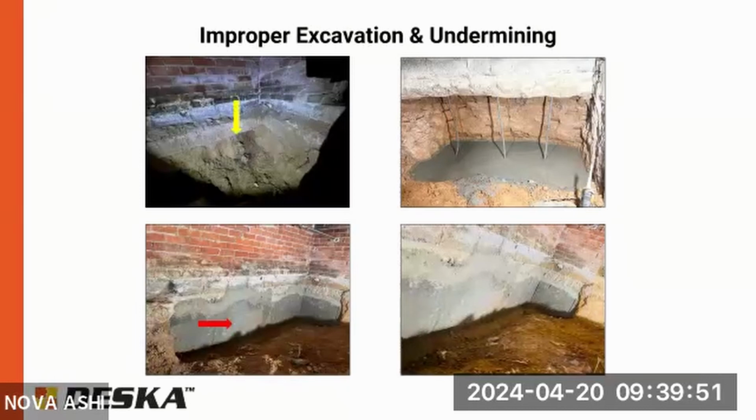Typically, before the footing can be poured, an inspector has to come out, probe the soil, make sure it's suitable, and it meets the design requirements of the footing. In this area, it's 1,500 pounds per square foot, but it varies depending on where you are, and also if you have a geotechnical investigation, you can use a different standard as well if it's determined to be adequate.